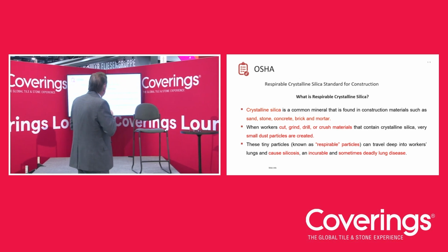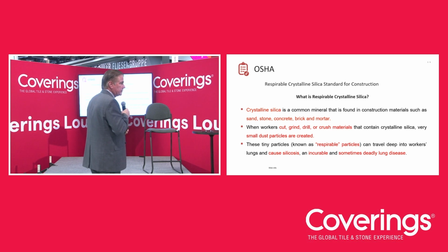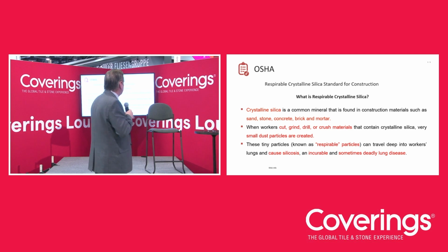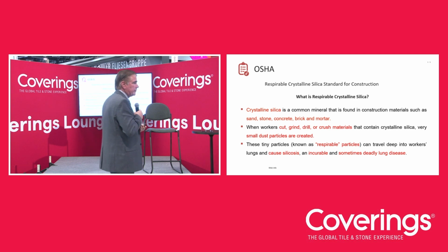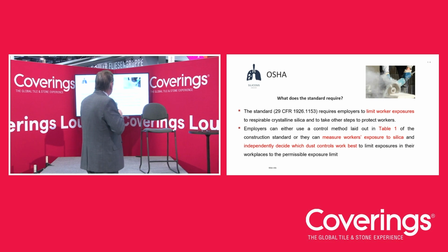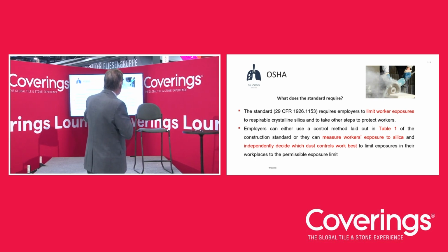OSHA has a standard for respirable crystalline silica. It's a common mineral found in construction materials such as sand, stone, concrete, brick, and mortar. When workers cut, grind, drill, or crush these materials, very small particles are created, and that's what creates the hazard. OSHA's standard requires employers to limit worker exposures to respirable silica and take other steps to protect the workers.